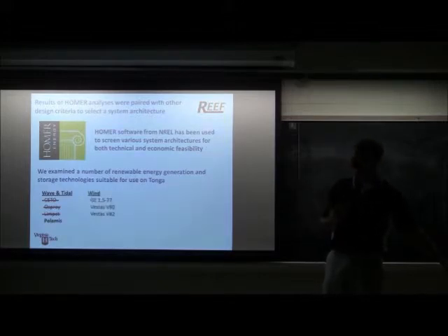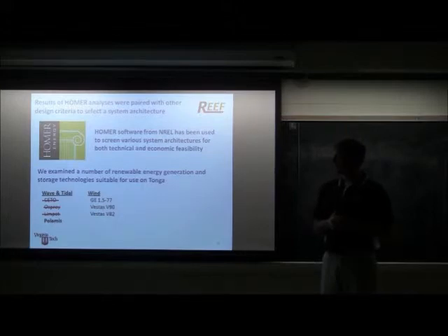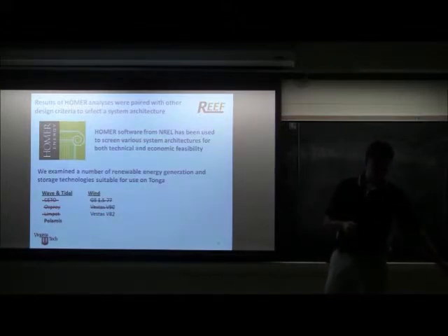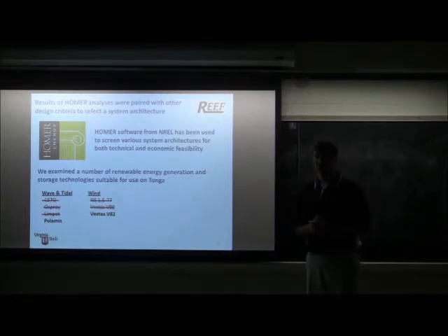We next looked at wind turbines, ranging in size from 1.5 megawatt GE turbine up to 1.8 megawatt Vestas turbine. And from our economic analysis, we concluded that neither the GE nor the Vestas V90 was the best option, but rather that the Vestas V82 would fit our purposes well because it is optimized for the type of wind speeds that we expect to see on Tonga.